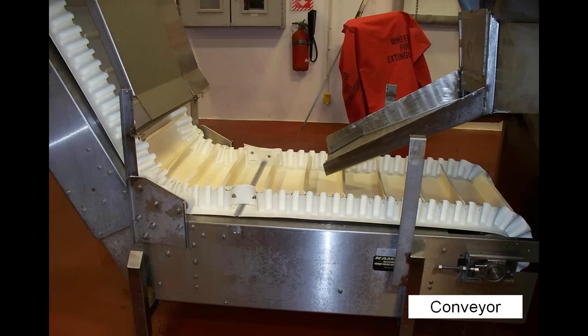And as we look at the conveyor, what can I say? It's almost like, what's wrong with this picture? Lots of places to start. Sandwiches, inadequate standoff, a closed framework, floor clearance, stitch welds, and again, the big chute on the left that is guarding the product going up the conveyor. How could that be removed, and how do you clean the backside of that chute?